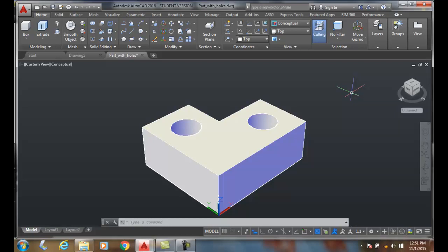So our view cube is a handy tool. It's always here, and I can just pick on the sides, which have the names, to get to any particular standard orthographic view, or I can go in the corners to pick isometrics. And I can also pick halfway in between my ortho views by going on the edges. I can use the compass and I can use my direction arrows to spin around. And anytime I want to come back to square one, I go back to the home view, and that brings me back to my initial default view.